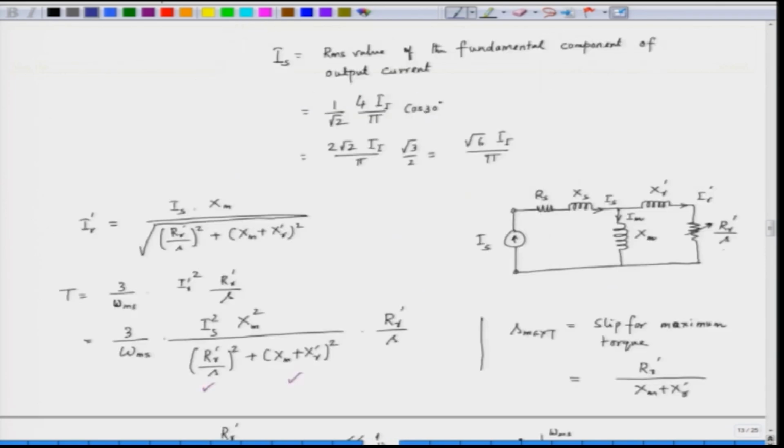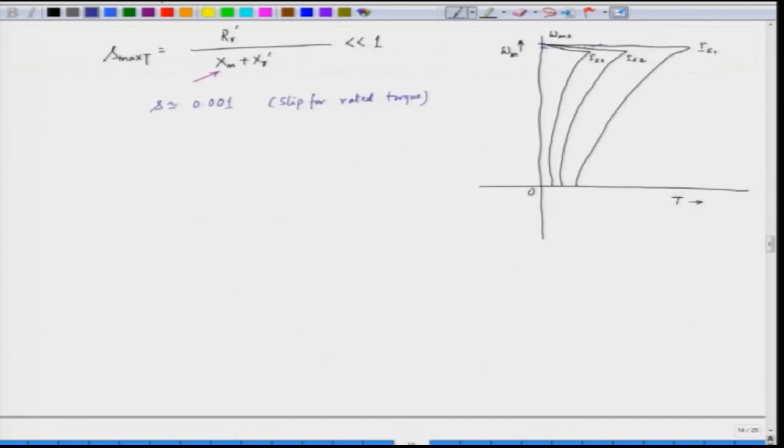Now, if you see the equivalent circuit, when slip is very small, the slip resistance is very large. So, this quantity, the resistance becomes large. Since the resistance becomes large, current predominantly flows through the magnetizing reactance. So, this leads to saturation of induction machine. So, at this point, although we operate at the rated torque here, the machine is heavily under saturation.